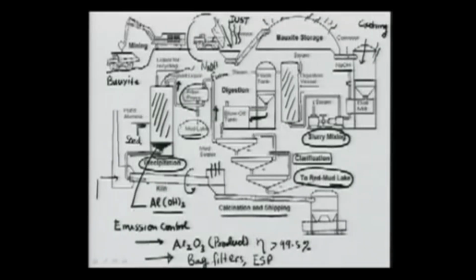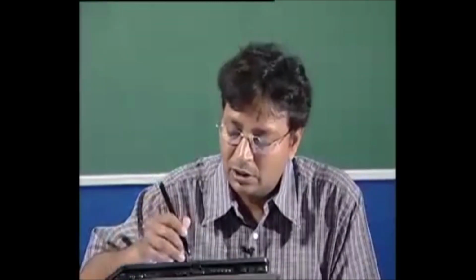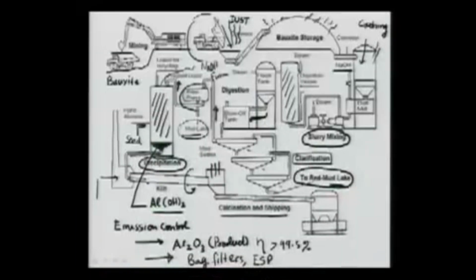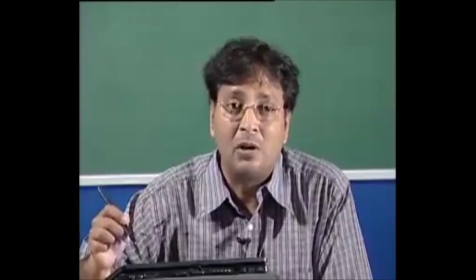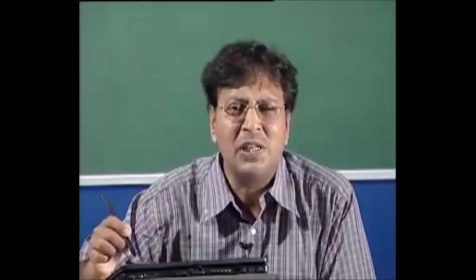And so what we can quickly see are the sources of pollution. That's what is of interest to us. Let me pinpoint for you. Source of pollution is the dust emission. Source of pollution is the bauxite storage. Source of pollution is also, let's not forget, the conveyor belt. So we need to control all these sources. We can't say, well, this is not a major source. These are major sources. In fact, an alumina plant not really well maintained is hugely dusty.